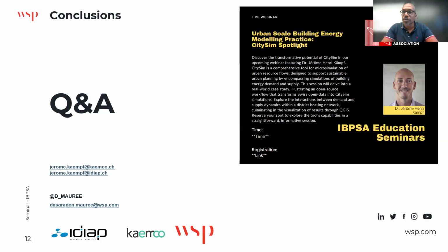And the second part of the question was how many? So is each building a single thermal zone in CitySim, or does it have multiple thermal zones? Yes. Oh, okay. So one building is a thermal zone. Typically, we would do that. But it is possible to also discretize each floor as one zone. So you can also do that if you want to have more precise energy calculations.